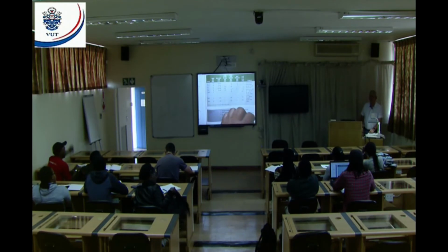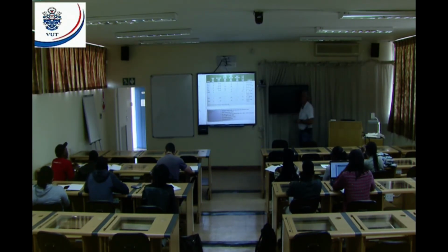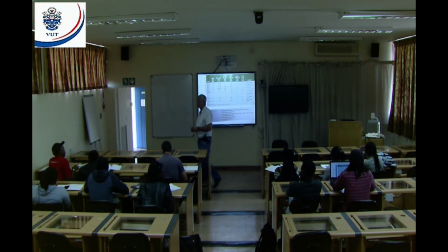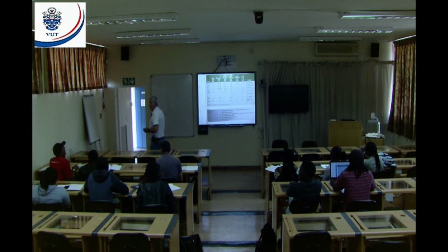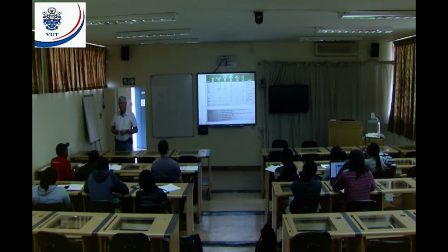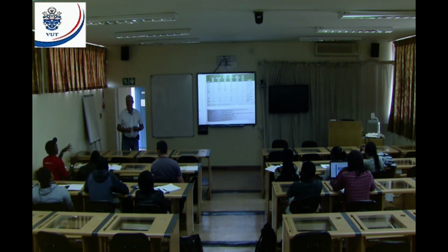Any questions? Yes. So here, for the LM741C, the open loop gain is 106. It's in dB. If you convert it, you will get its value also equal to 200,000. It's just expressed in dBs, all right? So is it necessary to know, maybe for the LM741, the common mode rejection and the open loop gains?